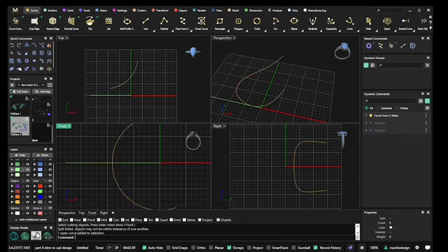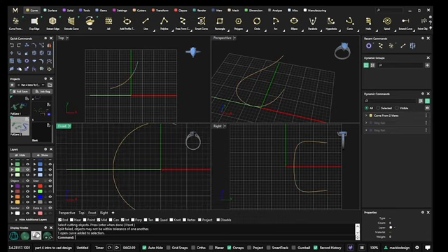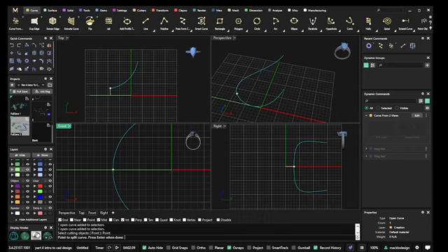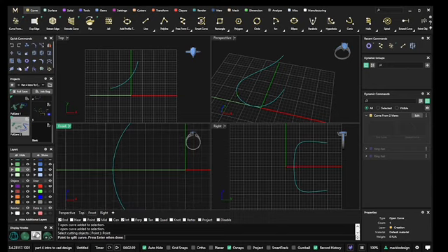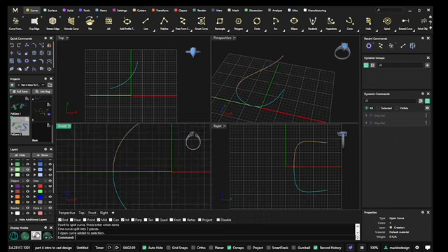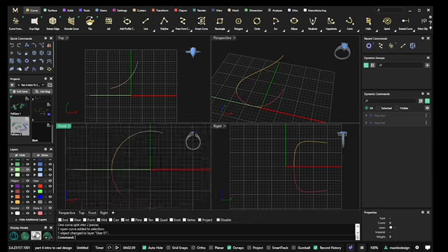That happens sometimes. So what I do then is I select that curve, go back up to split, and I want to split with the point. So I select point and my O snaps are on, and look at that, it wants to snap right to mid. So I click, press enter, and voila, there we go.